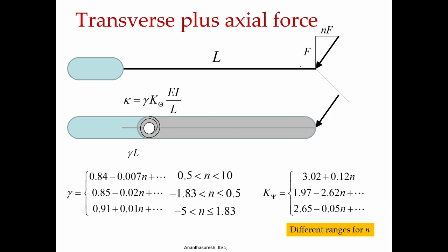If you remember, I also showed this spread of these points of the locus. When they took that and approximated with a circular arc, because that was already known, they tried to see what is the best circular arc radius and where should that be. That is, they tried to obtain this value gamma, what we call characteristic length factor, that is from here to here will be this gamma L, where gamma they took as 0.85.